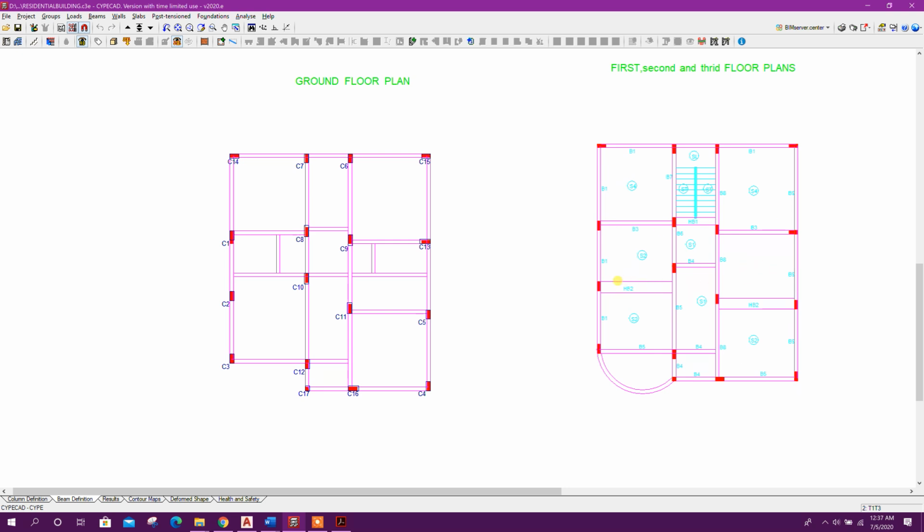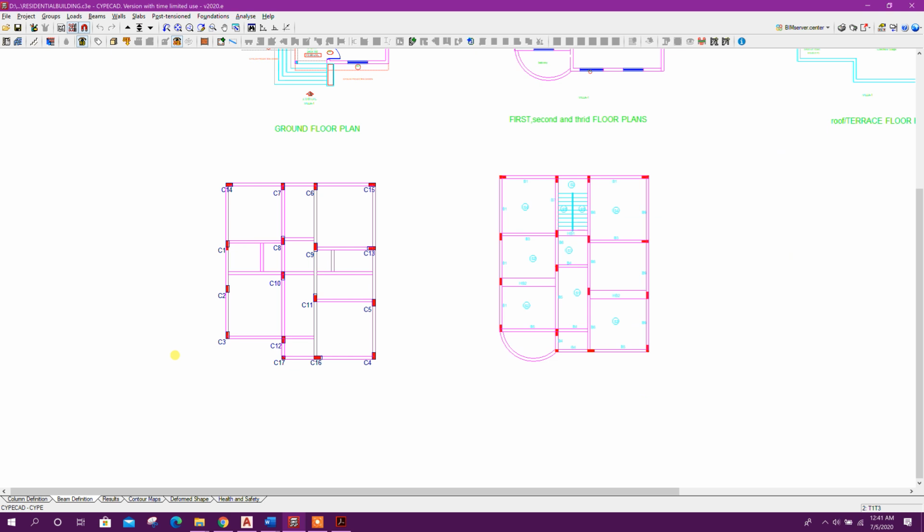Here these are hidden beams. These hidden beams are provided because we don't want to see the beam dropped inside the room where there is no wall. Here we can copy beams from plinth beam level also. Then we will keep similar beams here, and other beams we will delete.